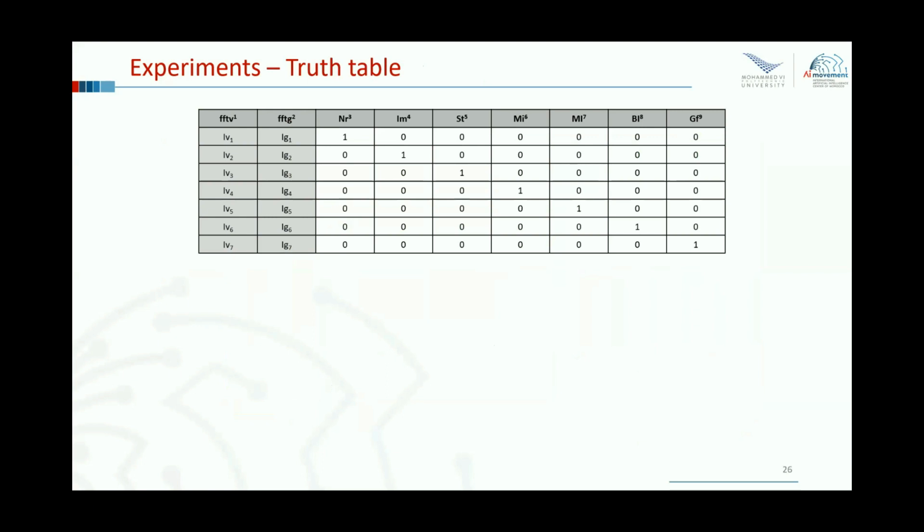So with the help of the experts and based on the knowledge, this is a truth table which represents which state corresponds to the 2 input variables, velocity spectrum and acceleration spectrum, using the AND operation. We only selected the existing cases. So when the velocity spectrum value is inside the interval EV1 and the acceleration spectrum is inside the interval EG1, automatically the machine is in its normal state.